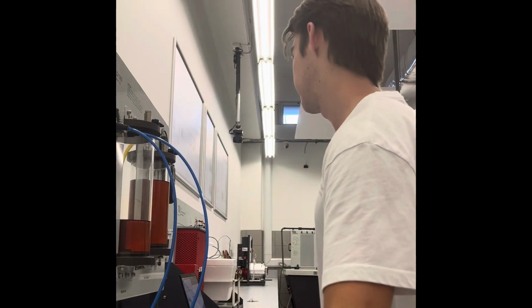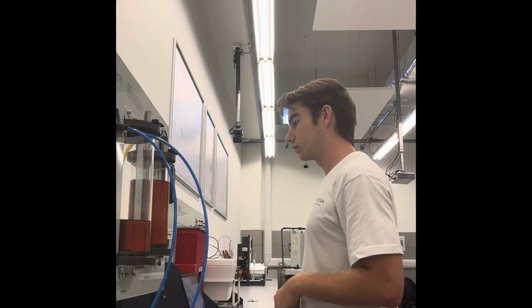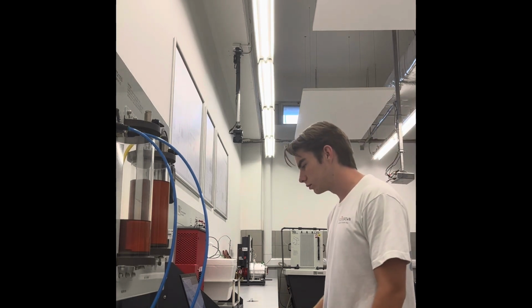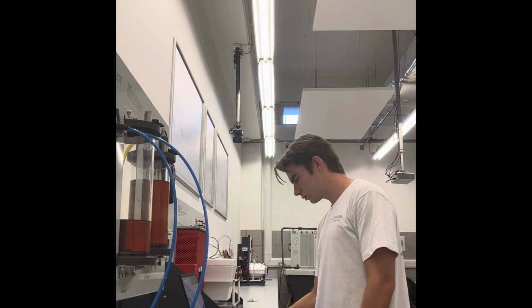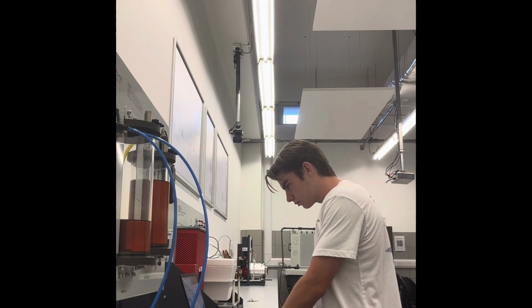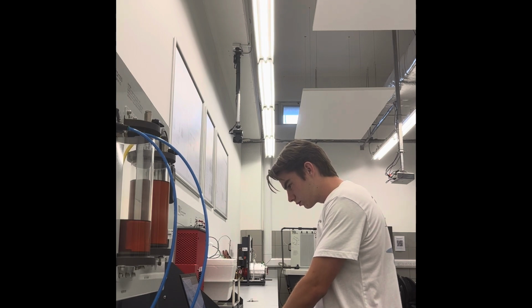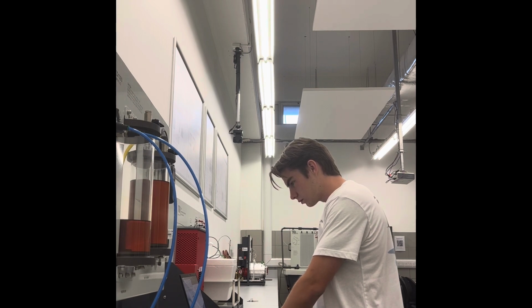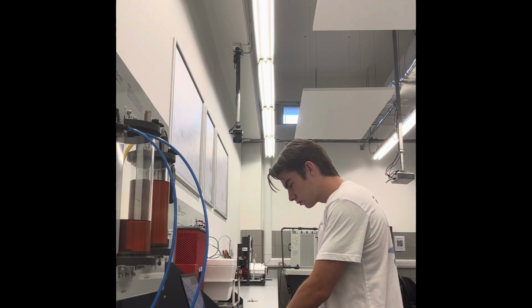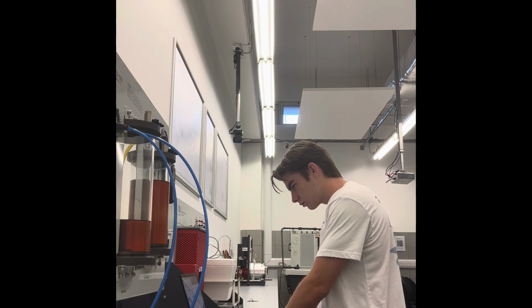Now, the important thing of this experiment is keeping both of our cylinders at a constant temperature. So I'm currently waiting for the temperature to even out, because when I increase the pressure, the temperature rises slightly. Once that temperature gets back to a good level, which I think was around 27.9 degrees Celsius, I'm able to look at the height once again and enter the data. As that volume's decreasing, I can move the height meter to measure the volume change that occurred, and then I can enter it into my table.